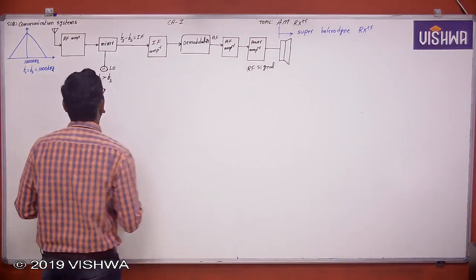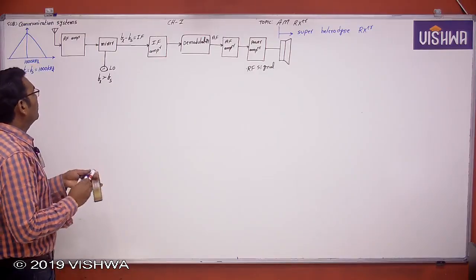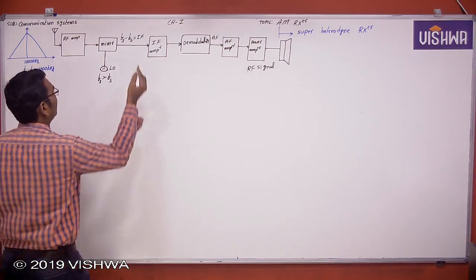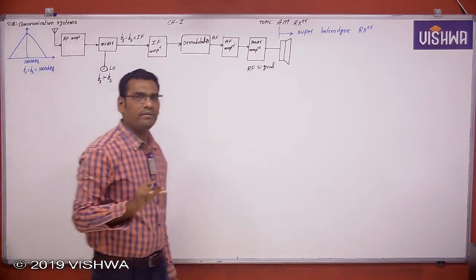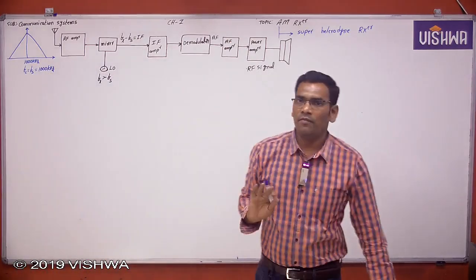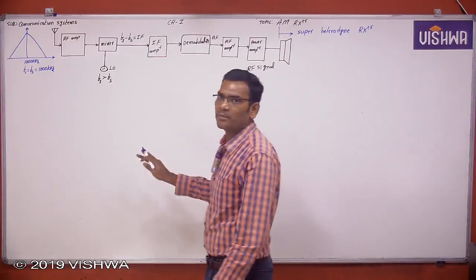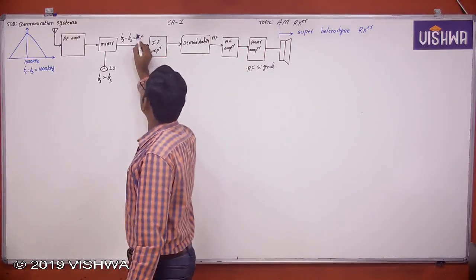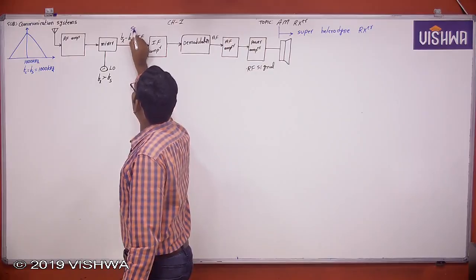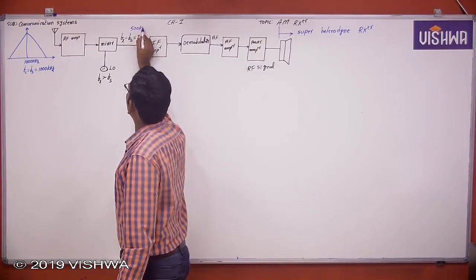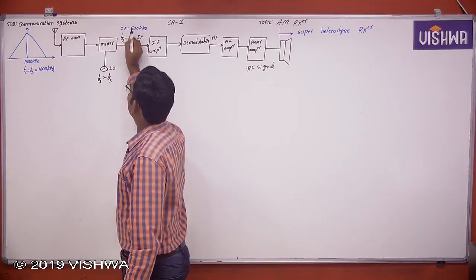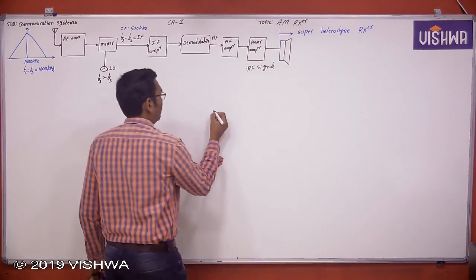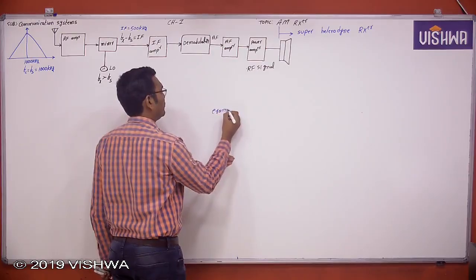Now see here. What is this intermediate frequency? The intermediate frequency is 455 kilohertz actually. Now for easy explanation of this analysis, I just take this IF as 500 kilohertz. Let us assume this IF, for example, for explanation of this operation.